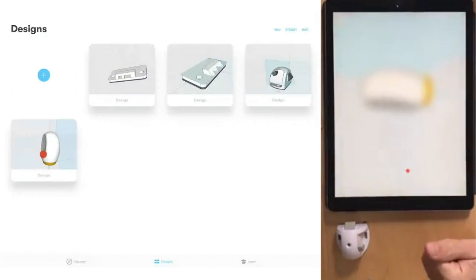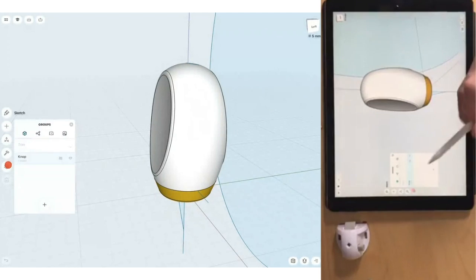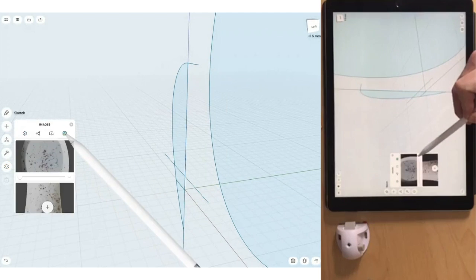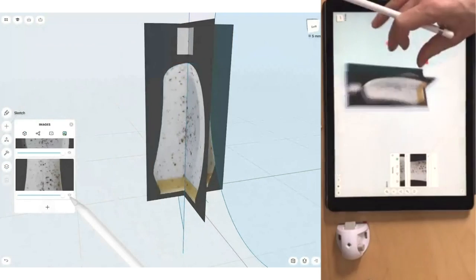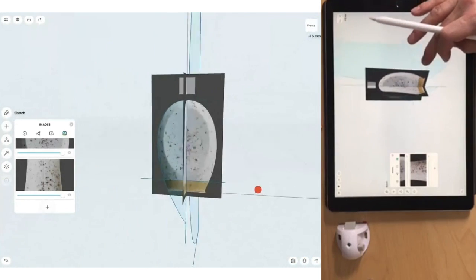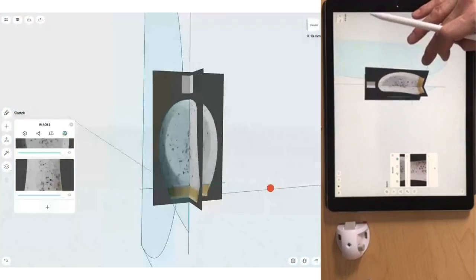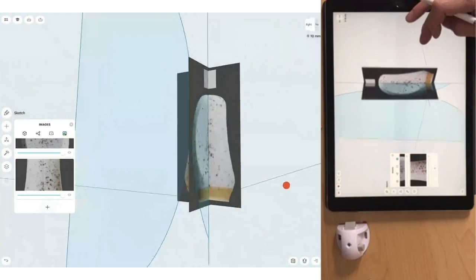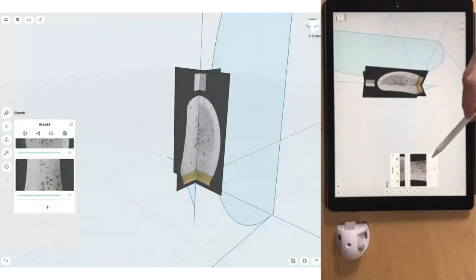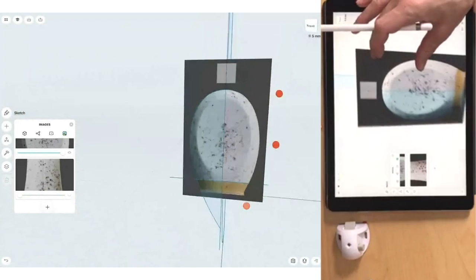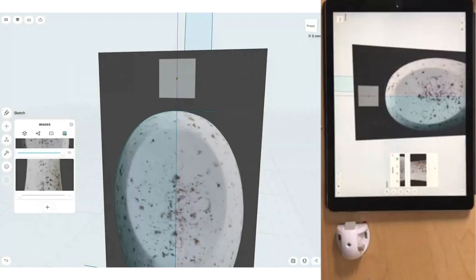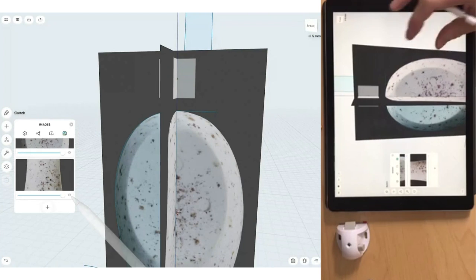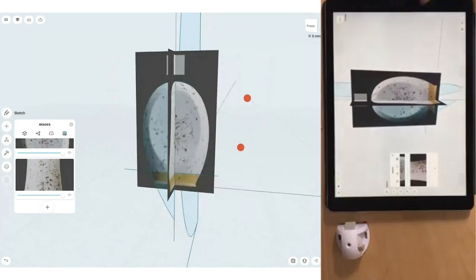So with side views, let me quickly go to here for a moment so I can show you what I mean. There are the two images. So if you bring over the images, it's also a good practice, like what I did here, to have a reference object. So I put in a square that's 1 centimeter by 1 centimeter, which I can use to measure. So once I draw a rectangle and scale the image to the rectangle, then I actually know that my image is scaled to the correct size.